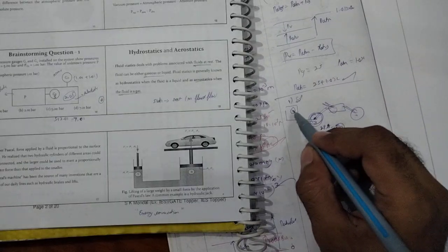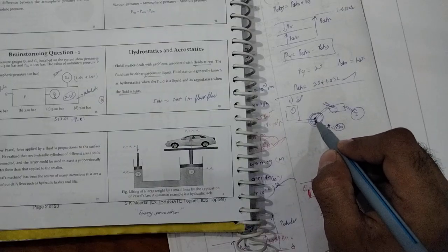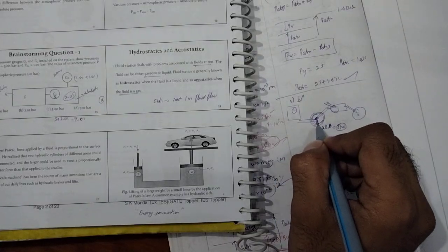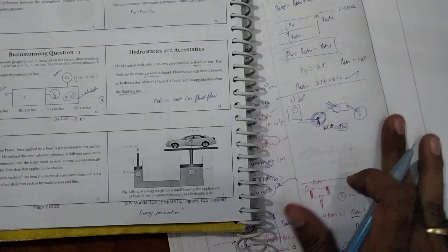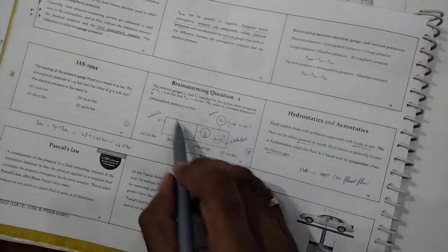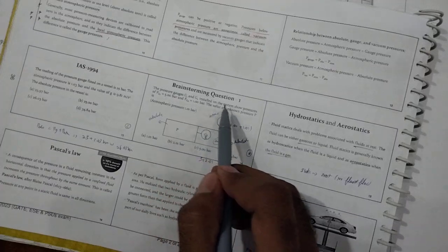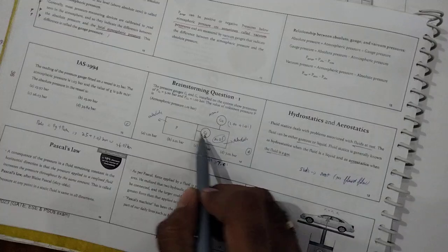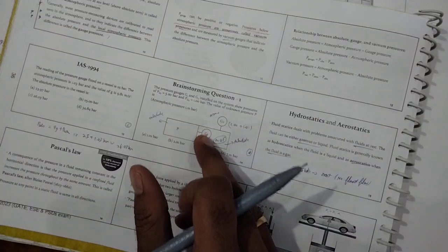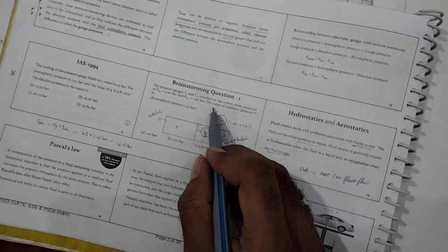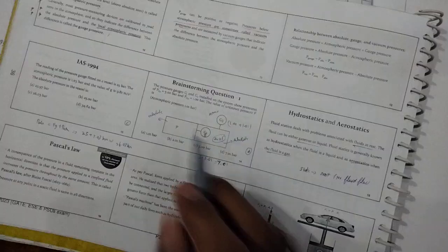So based upon the air coming in, the pressure gauge reads it. In the same way, how much pressure the inside has is read by the pressure gauge located there. The same thing has been shown here. You can see here, guys, pressure gauges G1 and G2 are installed on the system. PG1 shows 5.5 bar, the inside pressure, and PG2 is shown as 1.00 bar. So what is the value of this P? You have to mention it. I'll write it here so you can have a better and clearer understanding.